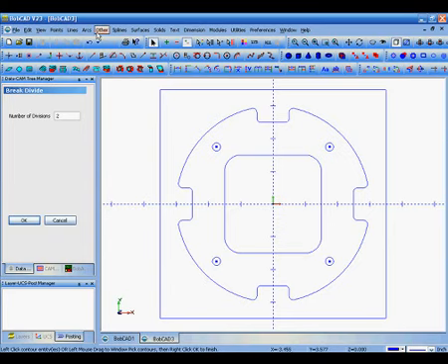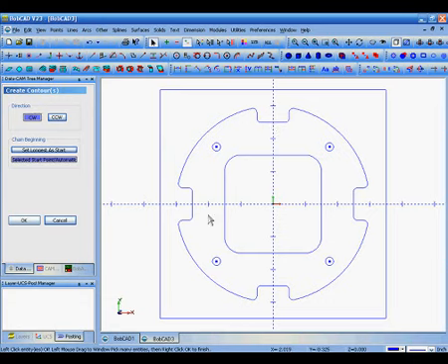So we're going to click on Other, Contour. What this will do is it will group the objects together, which will be the shape, and also set a direction. In this case, I'm going to go clockwise. I'm going to use Automatic or Select Start Point Automatic. Hold down Shift to do chain selection, and click the end of the last line of cut. Then right-click and left-click OK. And this groups the entire object together and sets a direction. Now we're ready to actually start adding our toolpath.